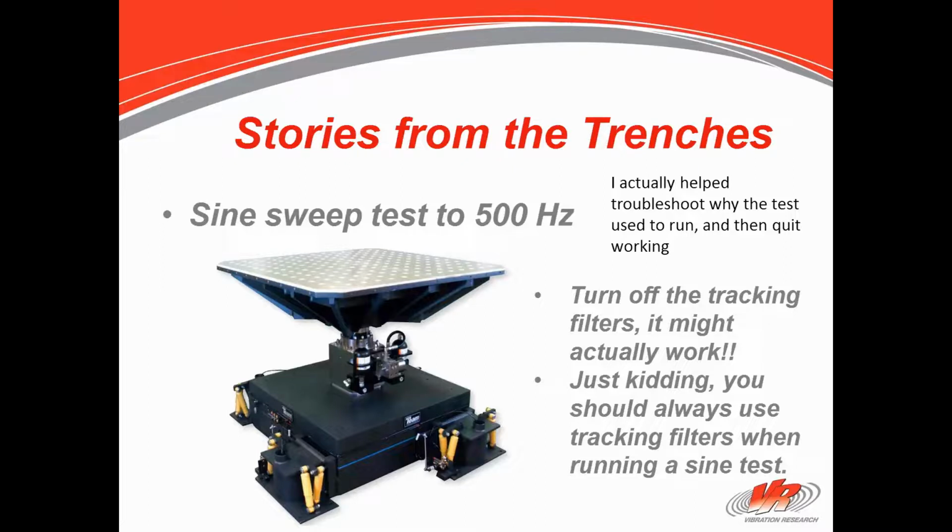So I'm telling this to the customer, and the customer, of course, says, no, we have run this before. So I'm scratching my head, how could they have run it and convinced themselves that they were running it? Finally, a thought occurred to me. I said, turn off the tracking filters. Go in the software to this place right here. You can turn the tracking filters on and off. By default, we turn them on, but perhaps someone had turned them off. So that's all I told the customer.